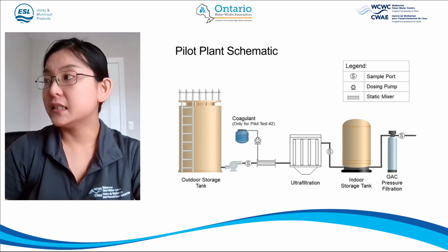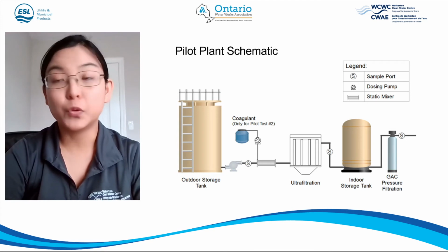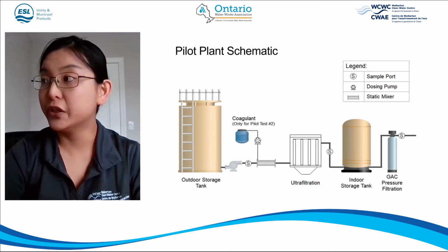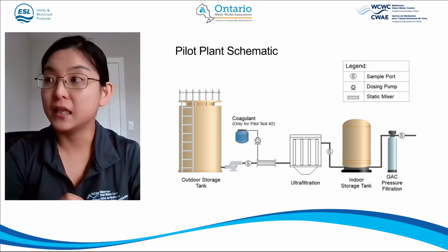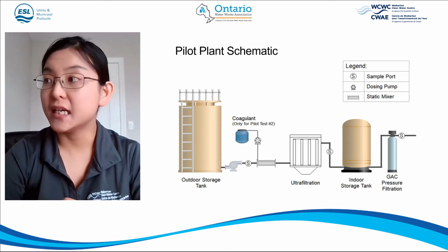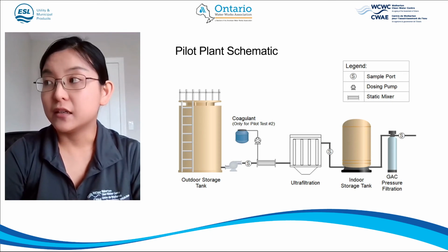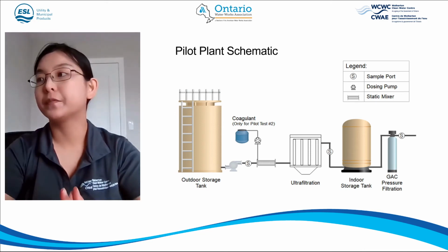During the test, the membrane had a nominal pore size of about 0.2 micrometer, and the effluent flow rate was about 9.3 gallons per minute. Transmembrane pressure was negative 1.4 psi, and the cycle was 30 to 60 minutes in between backwashes.